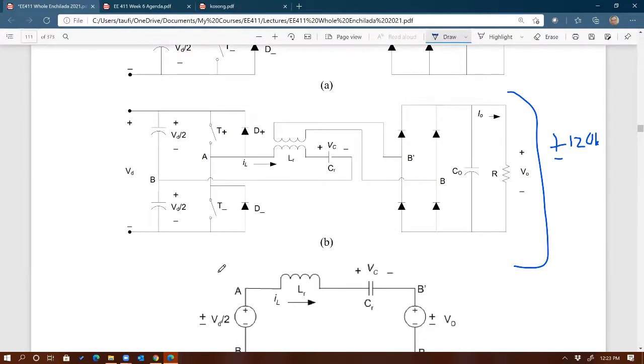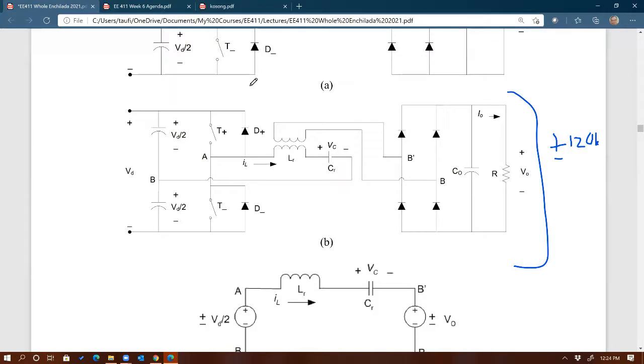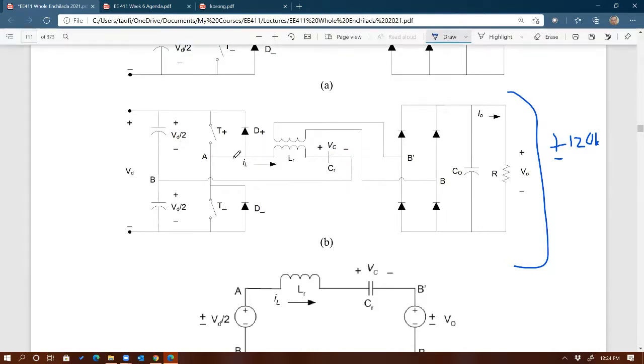Because voltage switches between 0 to 120 kV, right? Fast, and if that overlaps with the current, you can imagine the significant amount of switching loss that the topology will generate. So that's why for this kind of application, 120 kV, high voltage, high power, you typically don't want to use PWM topology anymore. That's too lossy, right? Switching loss-wise, it'll be too lossy, right?